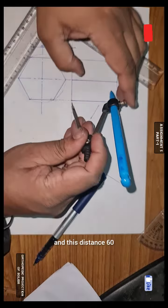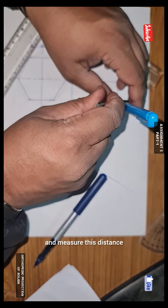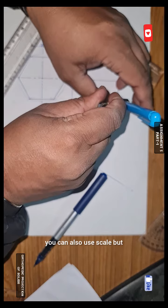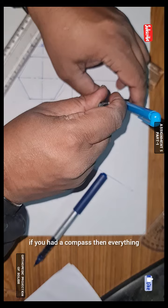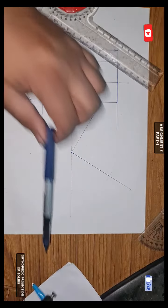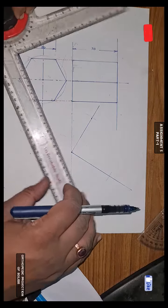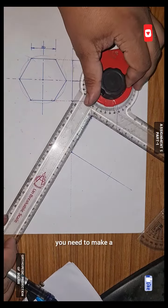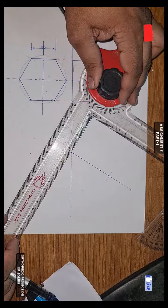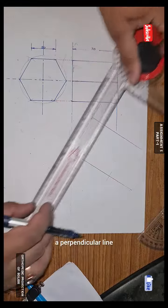And this distance 60, you take a compass and measure this distance. You can also use a scale, but there is no need. If you have a compass, then everything can be copied. You need to make a line over here again, a perpendicular line.